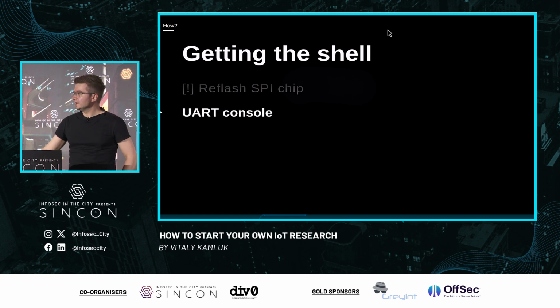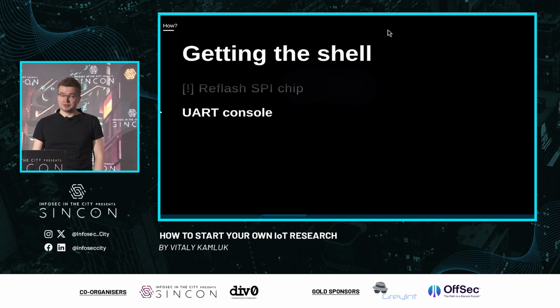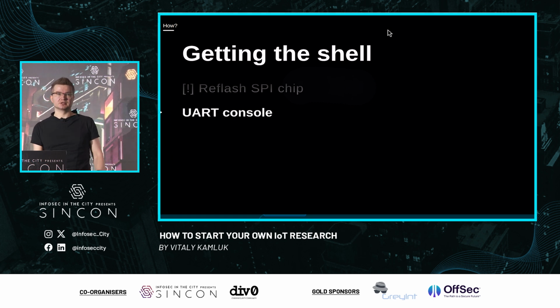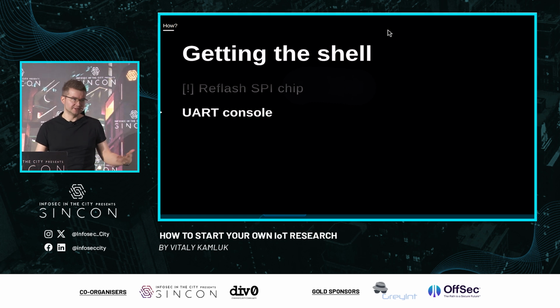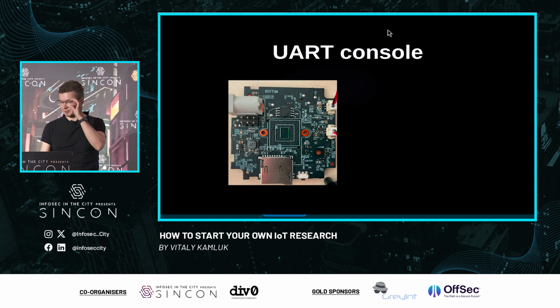So they often leave pins from this interface that connects directly to the system on chip, the SoC, and that allows you to interact with the device in a more organized fashion, so you can have an actual console, pretty much like you're attaching a display to the device. So over this serial communication, you can interact in text form. You can type commands and the device will reply.